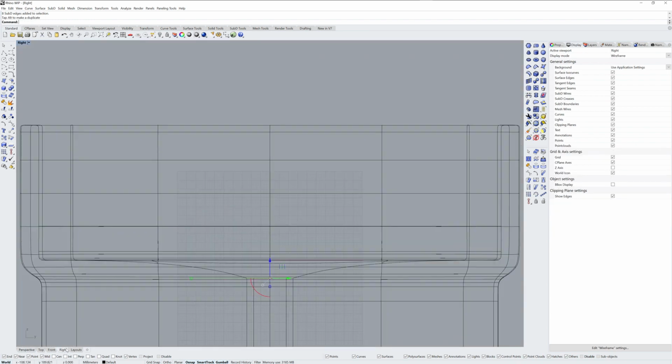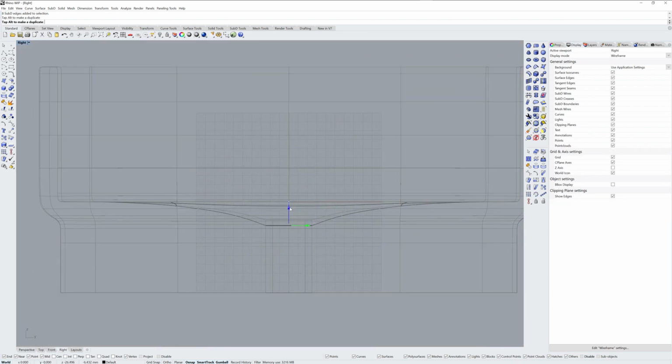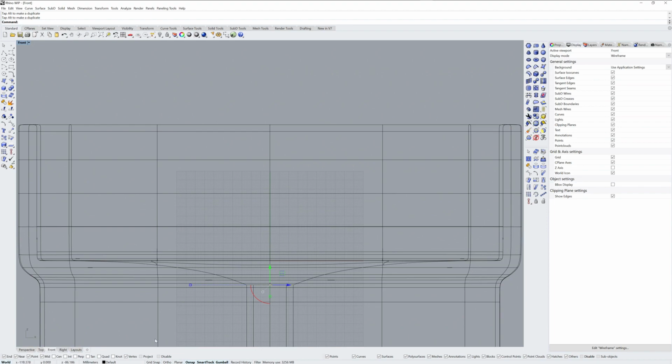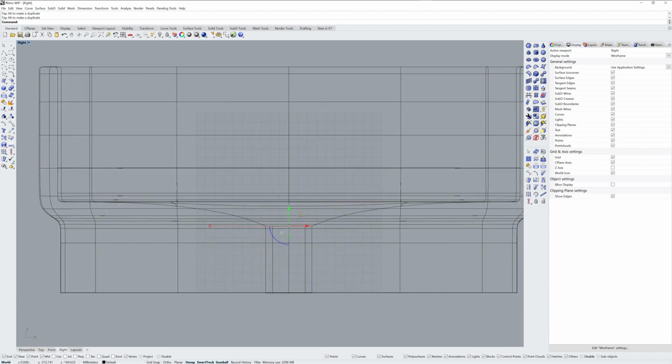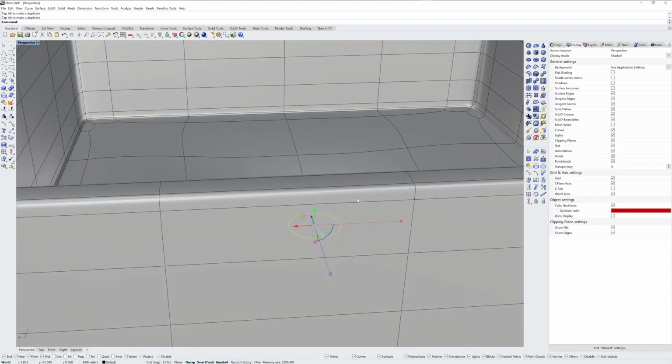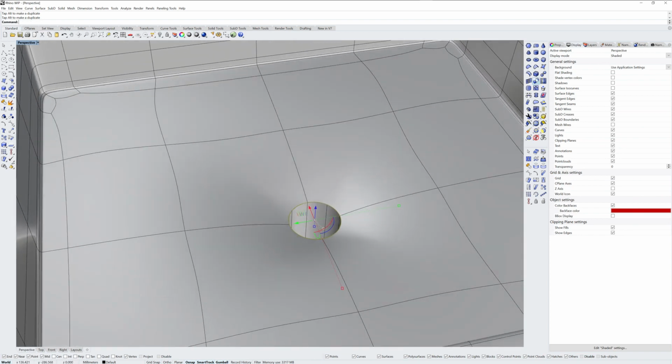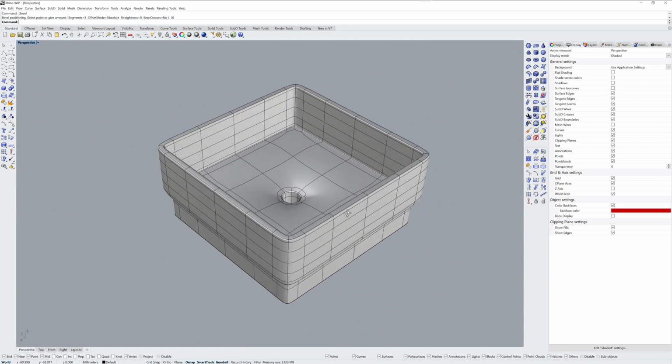Let me go into a right view in wireframe so you can actually see the slope that I'm adding here. And in front, like that, it'll be the same because it's same dimensions, something like that. And then I'll finish it with a bevel here and maybe just do a numeric 10 millimeters. There we go.